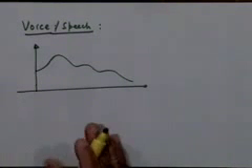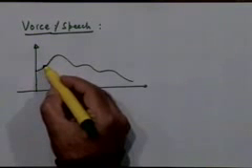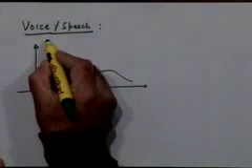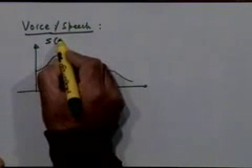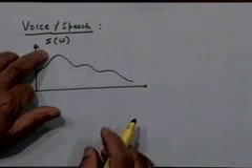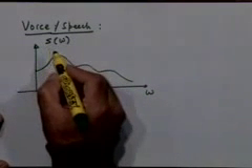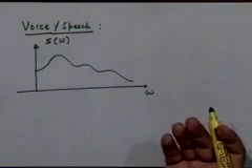We see that the spectrum has this kind of a nature. It builds up from low energy at the lower frequency end. So this is typically the notation for power spectrum, S of omega as a function of omega, right? So if I plot power spectrum, then there is no question of phase, because power spectrum only gives information about the distribution of power as a function of frequency, right?